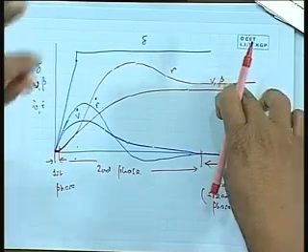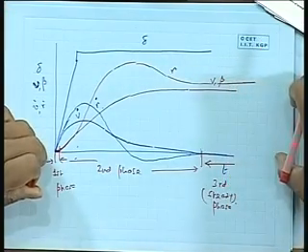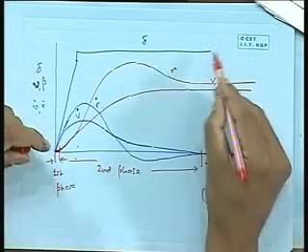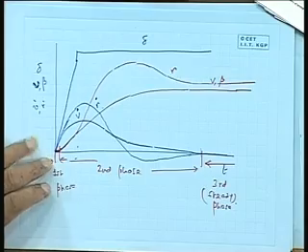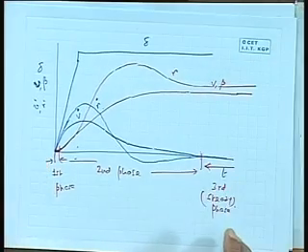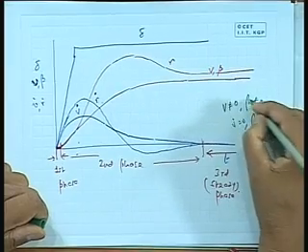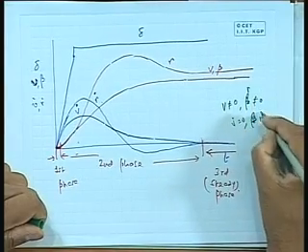If you recall, earlier we turned the rudder, waited as long as we wanted till r became a fixed number, which is this one, then it does not change anymore. Then I changed the rudder again. That is how I proceeded. Okay. So it becomes like this. Now, what happened? From this we can of course analyze the ship's behavior, and we will go into a little bit of maths, very little maths, to tell you something regarding this phase. You see, this phase is most important, because in this phase I have v not equal to 0, beta not equal to 0, but v dot is 0, r not equal to 0 and r dot equal to 0.